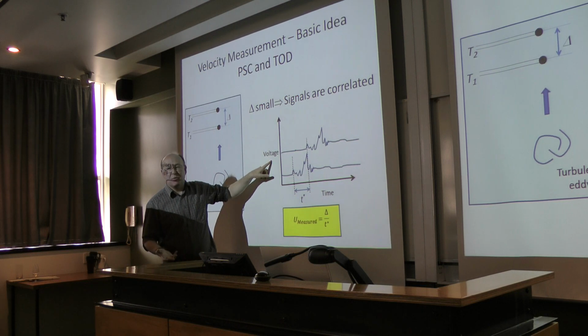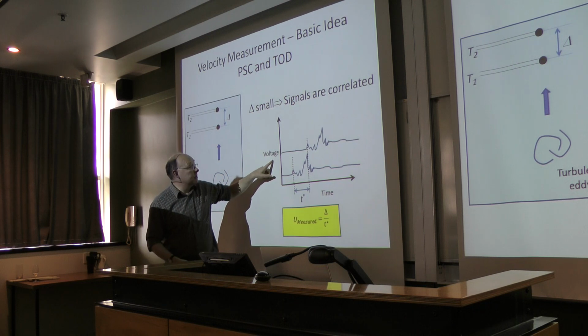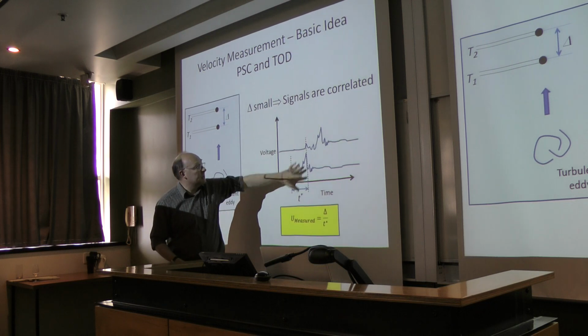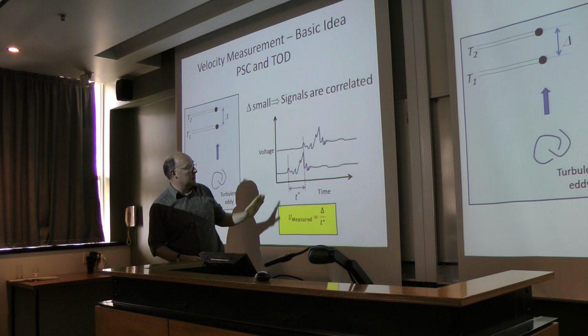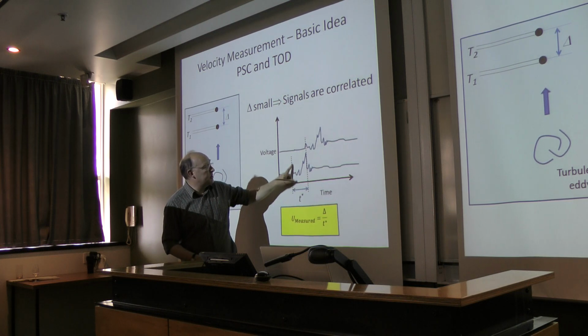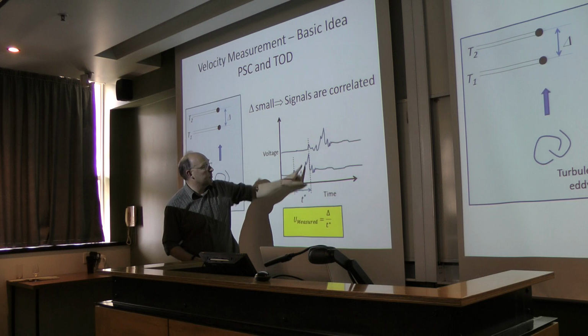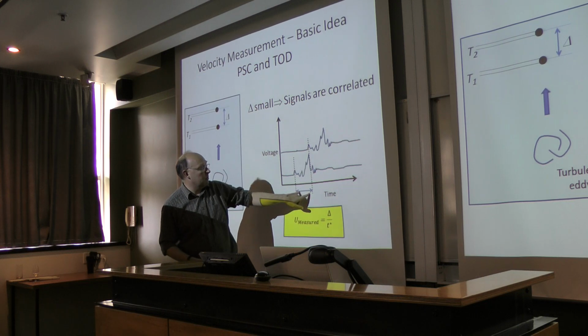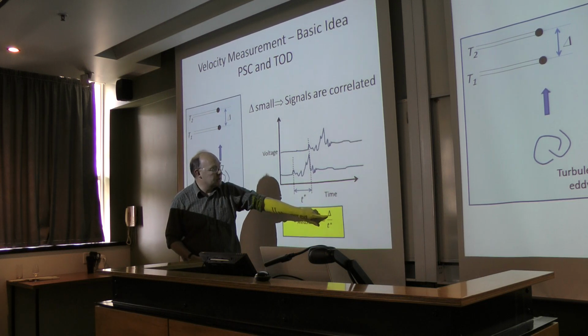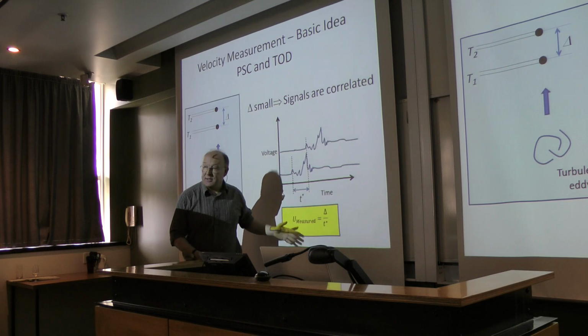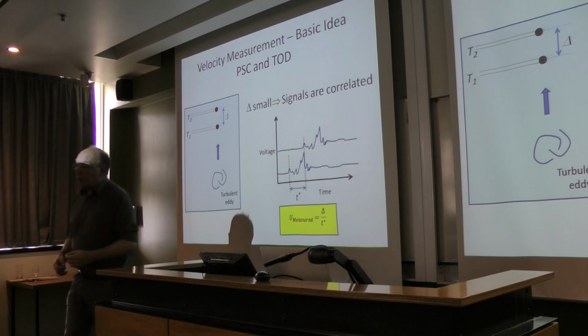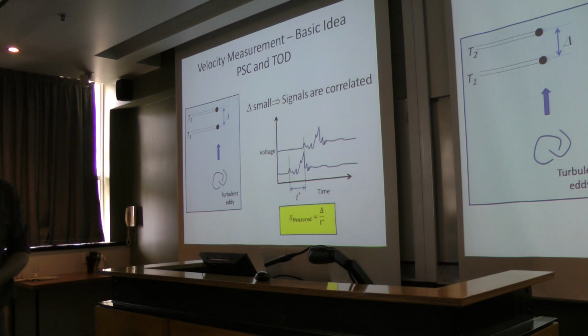We're interested not in the temperature. I use the voltage because it's a bit quicker. I can log more quickly with the voltage. Then, ideally, if I see something like this, that would be absolutely brilliant, because all I would have to say is, okay, well, the signal starts here on the lower thermocouple, the signal starts here on the upper thermocouple, then I know the distance between the two, I can get the velocity out of that. That's the idea.